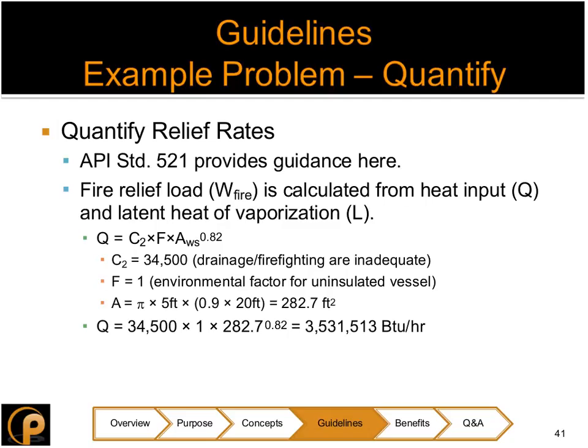If you're going to ask me personally, I would think a PSV would be more reliable than two regulators in series because there's nothing to guarantee, even though it may fall into the range of double jeopardy, that those two regulators are going to act properly, one to close if something else happens or one to shut down a little bit more than it needs to in case the one that's upstream fails open. You can still have a failure, you can still have an overpressure because of one of those two things failing. And in that case, you may still need a PSV or a vent.